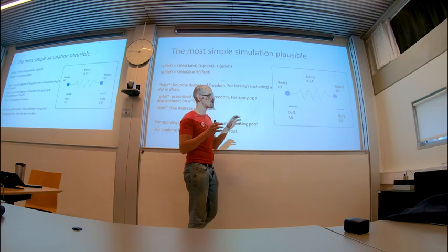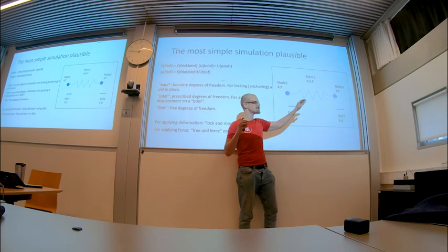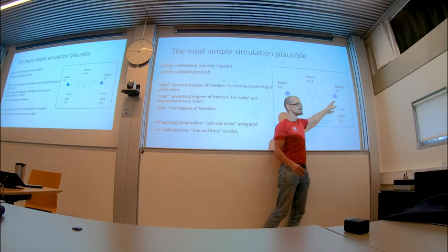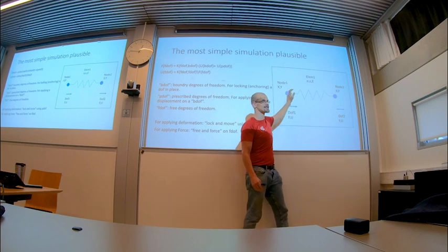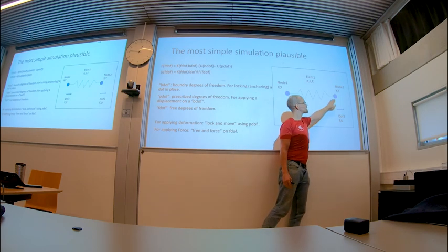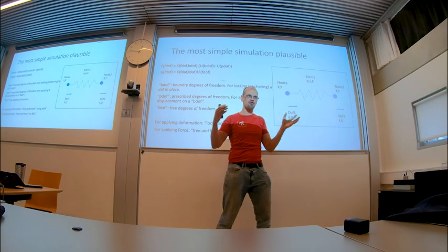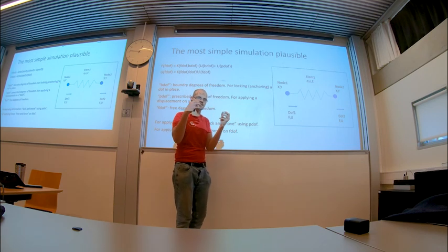But technically, all elasto-plasticity does this thing, where you have an elastic mesh, in this case a spring, and it's only forces that can really deform it. If something is anchored, it's static, it's done. But because only forces can deform it, you need to convert these plastic increments into some kind of force on the nodes that will shape it into the plastic deformation that you want.